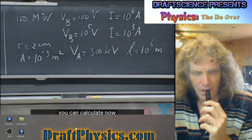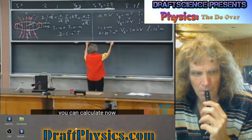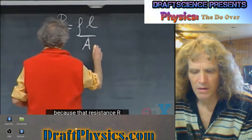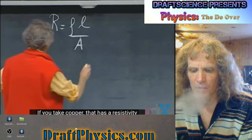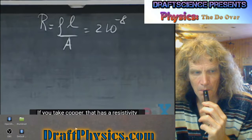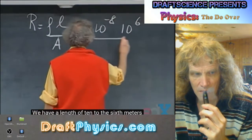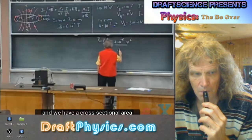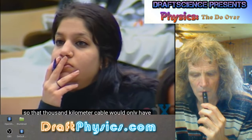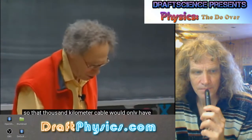You can calculate now what the resistance of that cable would be, because the resistance R equals rho times L divided by A. If you take copper, that has a resistivity of 2 times 10 to the minus 8 SI units. We have a length of 10 to the 6 meters of the cable, and a cross-sectional area of 10 to the minus 3 square meters, so that 1,000-kilometer cable would only have a resistance of 20 ohms.